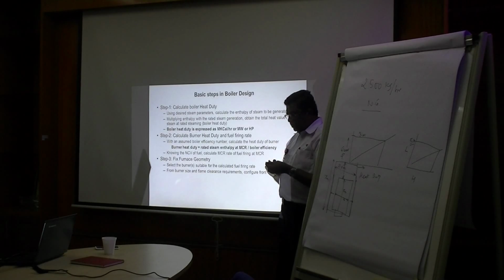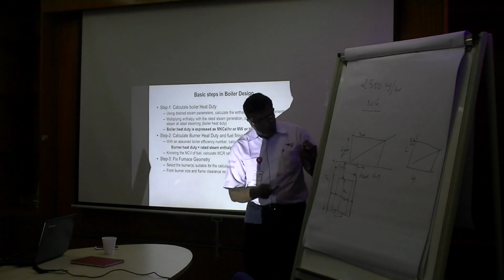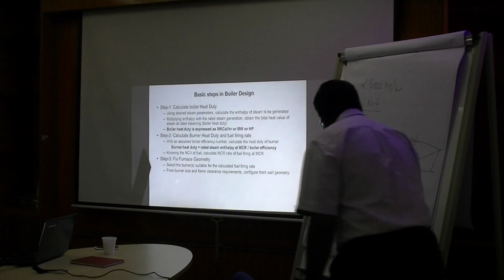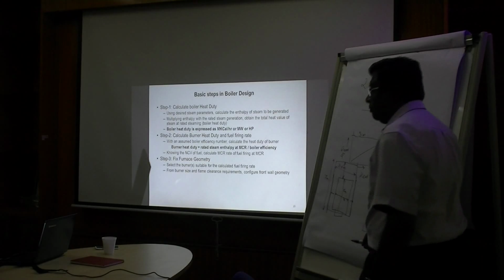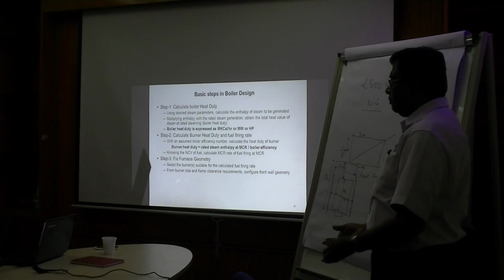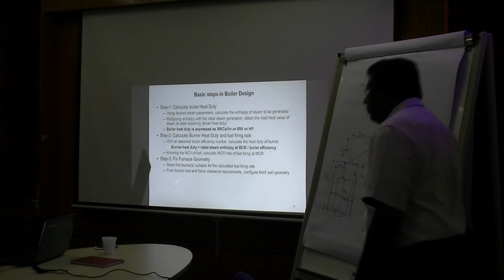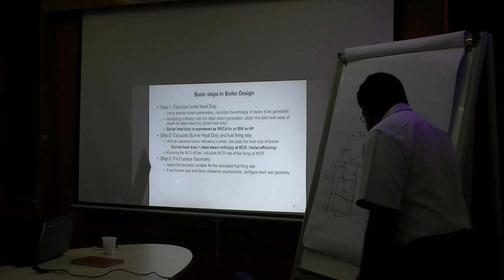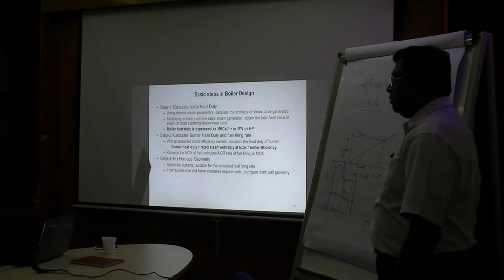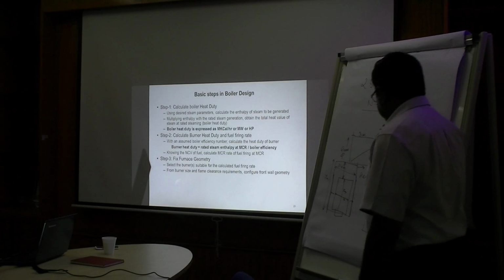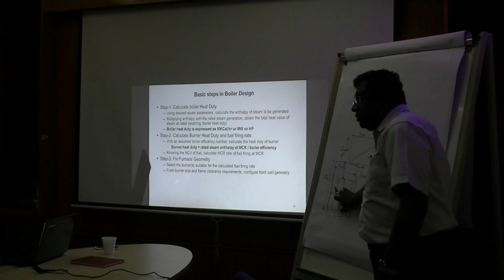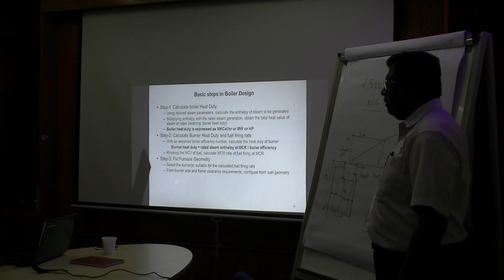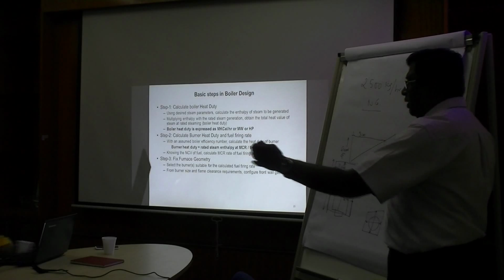Okay. Now, since we had only one burner in mind, let's try to develop the front view, the front elevation. Basically, this dimension and this dimension will be the same. There is only one burner, so it's a uniform circle. If this is the flame envelope, and we already decided this as 3 meter, this also will be 3 meter. So, from the flame geometry, we have come to the size and shape of the furnace. It will be so much deep, so much wide, so much tall.